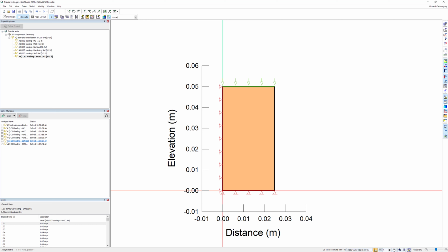Strictly speaking, cloning the isotropic consolidation step is not necessary here, since this step is unaffected by drained or undrained loading conditions in the following Triaxial tests. However, cloning it nevertheless allows for easier separation of both series of tests.